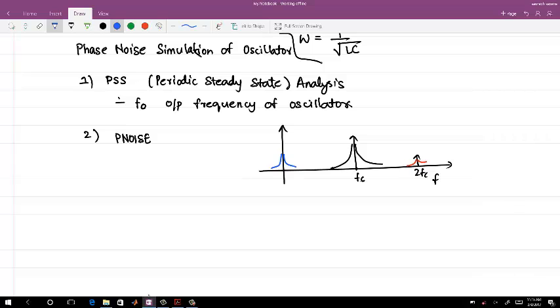Okay. So when you are doing a PSS analysis for all these oscillator purposes, you find the relative frequency. Whereas if you want to look at the noise at DC, then you will do an absolute, which is actually done in other systems like switch caps. Let's say you are having a switch capacitor filter, right? So when you are having a switch capacitor filter, you look at the noise from the DC. I think, have you done any other switch capacitor circuit or no?